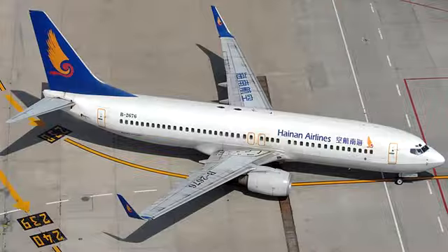With the increased size of modern airports, taxi distances have also increased, thus increasing the amount of tyre wear and risk of damage. To minimise tyre wear, it is recommended that a speed of no more than 25 miles or 40 kilometers per hour should be reached during the taxi run.